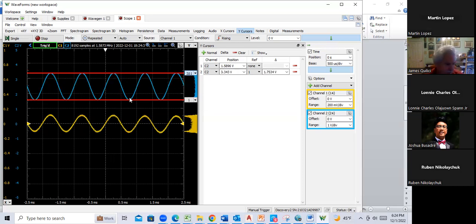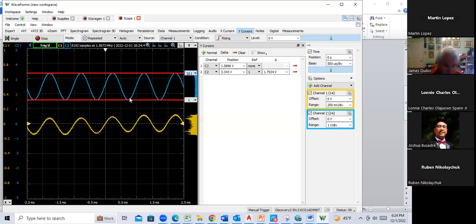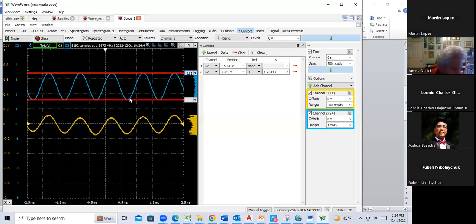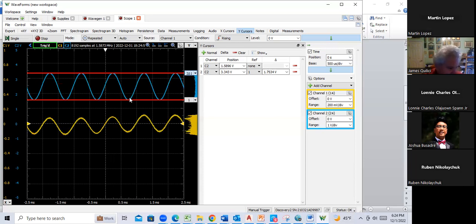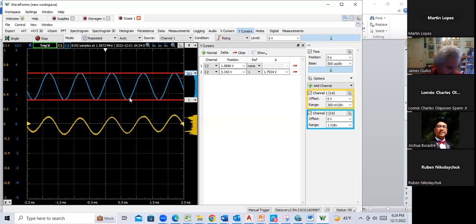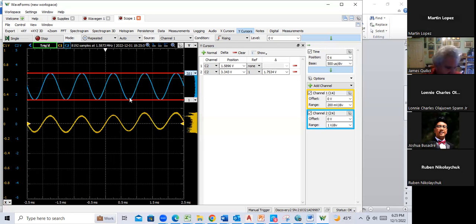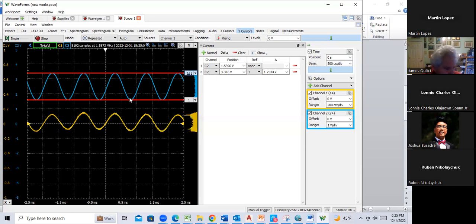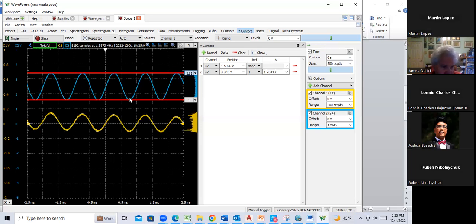Okay. So anyway, as far as doing this lab and making your measurements, I sat here, I had to dink around with it and tune it up. Part of the reason, again, is I didn't write down the values that I simulated last week. Hopefully you can start with your simulated values. And you might have to use resistors in parallel or series. Just try to get them as close as you can. What's always key, though, is getting the base voltage where you had designed it to be.